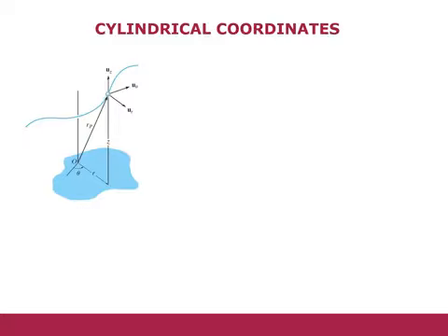Okay, we have studied the normal and tangential coordinate system. Now we are going to study the cylindrical coordinate system, that if our particle is moving in a curved path, then its motion can also be represented in a cylindrical coordinate system. In contrast to the rectangular coordinate system, where we have three axes x, y and z, in this cylindrical coordinate system we have the radial axis or radial direction, we have the transverse axis which is the theta direction, and we have the z axis.